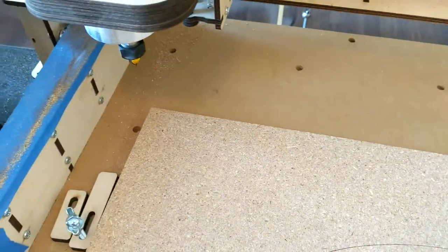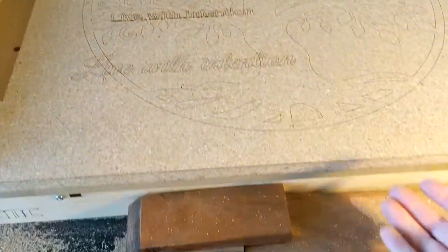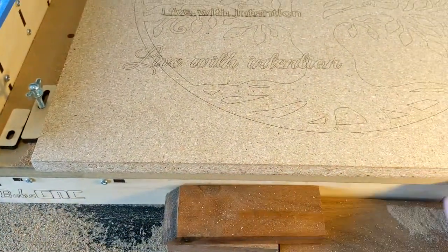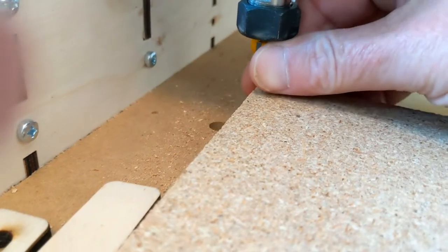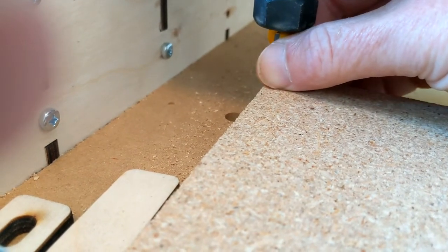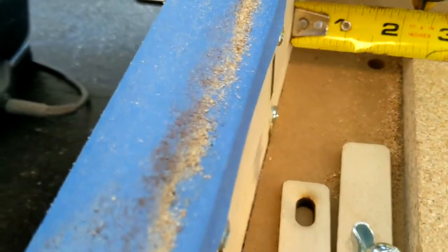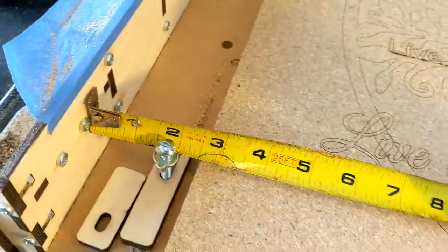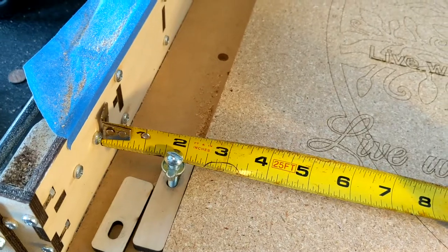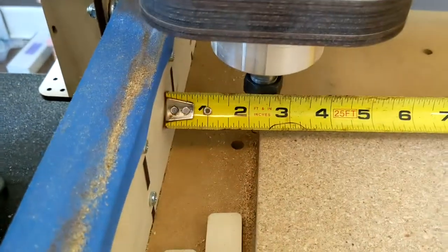Your workspace is from home position, which is right here, which I will set the board corner at that home position. And it can hang off, and it's only hanging off about 1/4 of an inch. So that's not so bad. So what I've done is I took my Z and I lowered it down to my part and simply just lined up the corner there. So at that point I measured it, which is 2 1/4 inches. And now I'll just adjust this side to 2 1/4 inches. Double check, back and forth, measure twice, cut once.